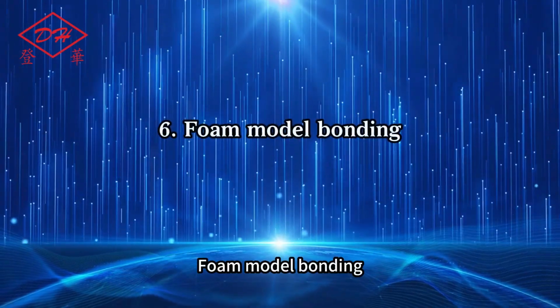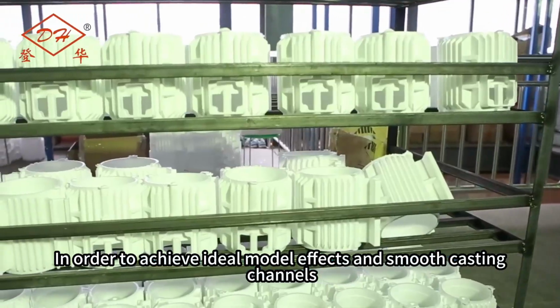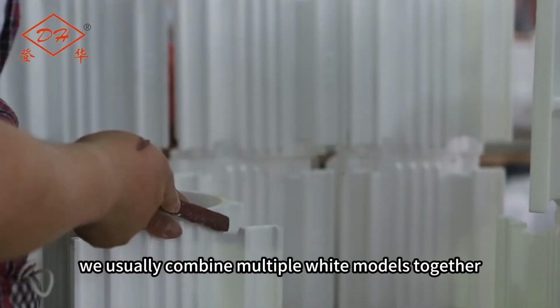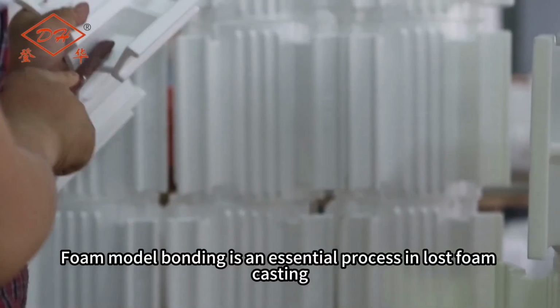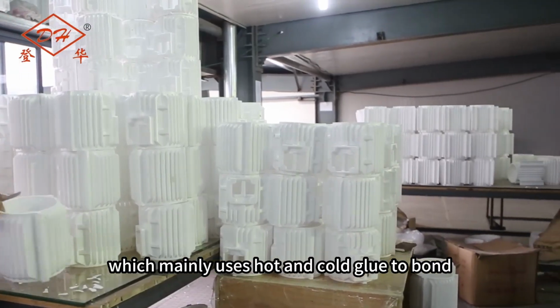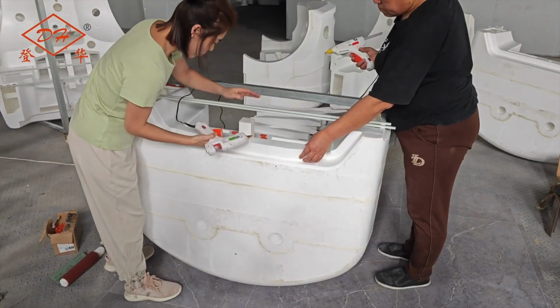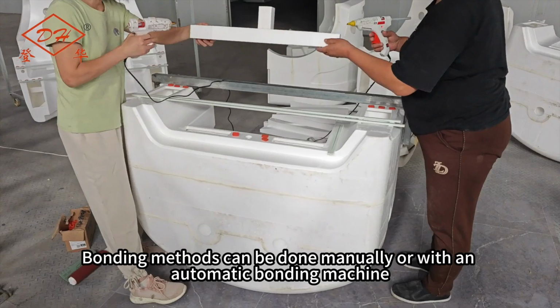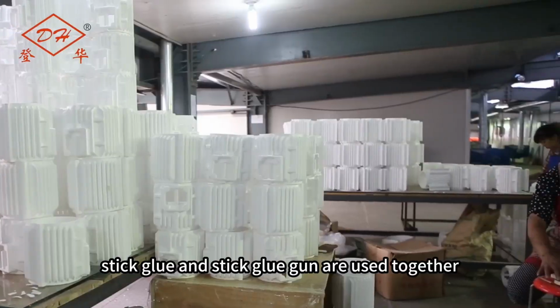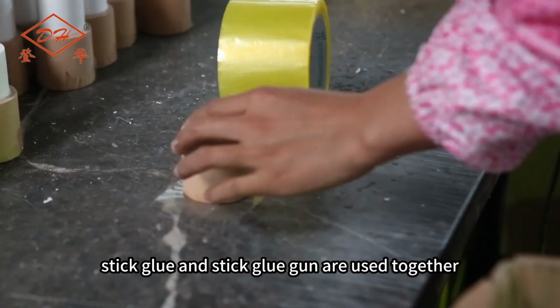Sixth, foam model bonding. In order to achieve ideal model effects and smooth casting channels, we usually combine multiple white models together. Foam model bonding is an essential process in lost foam casting, which mainly uses hot and cold glue to bond. Bonding methods can be done manually or with an automatic bonding machine. The use of stick glue and stick glue gun are used together.